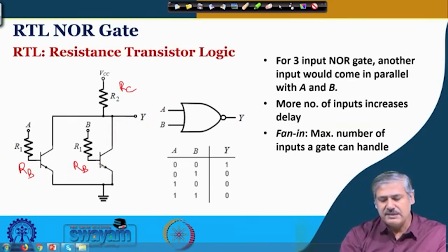Now, we look at the other case. So, these are the two cases that we have seen. This one is at high. Okay. So, this transistor is on, right. This voltage is clamped at 0.2 volt, this is getting a path. So, even if the other transistor is off or on, it does not matter, the output voltage will be kept at 0.2 volt. Okay.